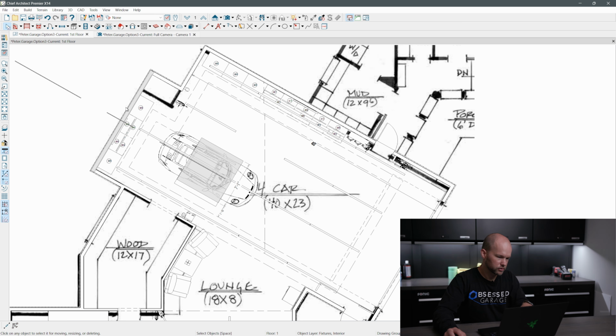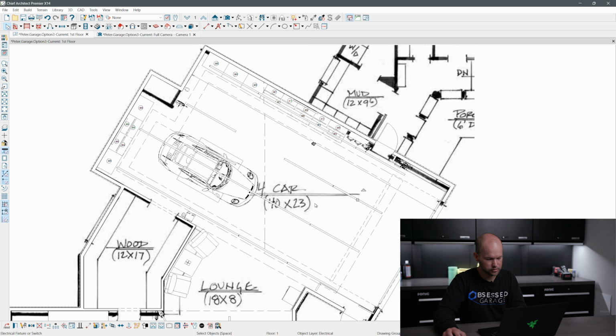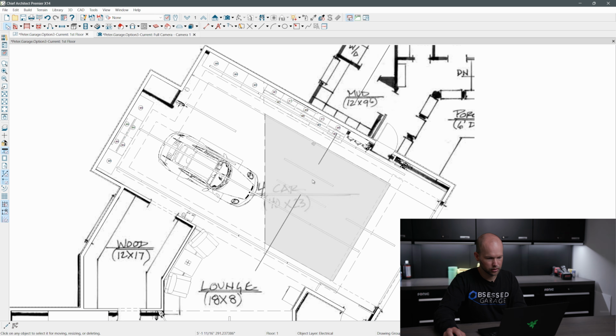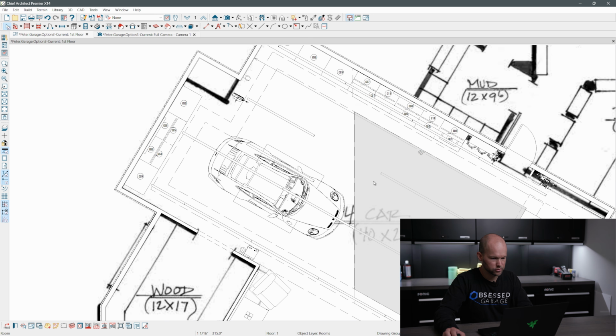Just like this. If you're using Chief Architect or Home Designer, you can do Control G, which allows you to align everything, which is super helpful. Like if I'm doing lights, and I move a light, say I have a light somewhere else, I've just placed it on here. Well, I can jump in here and move things pretty quickly to get lined back up, which is super handy.